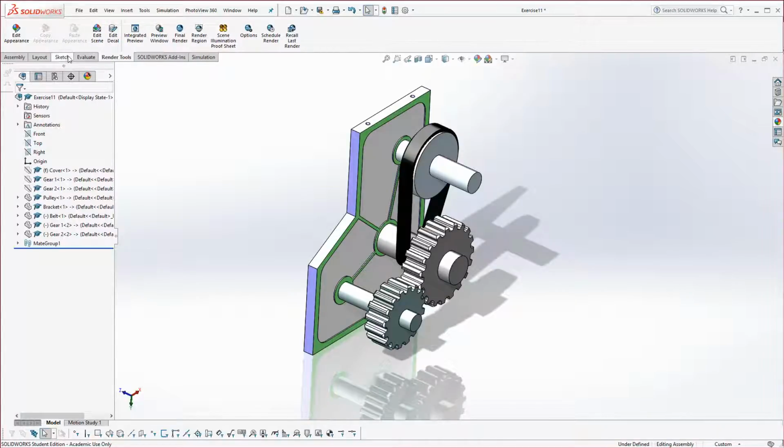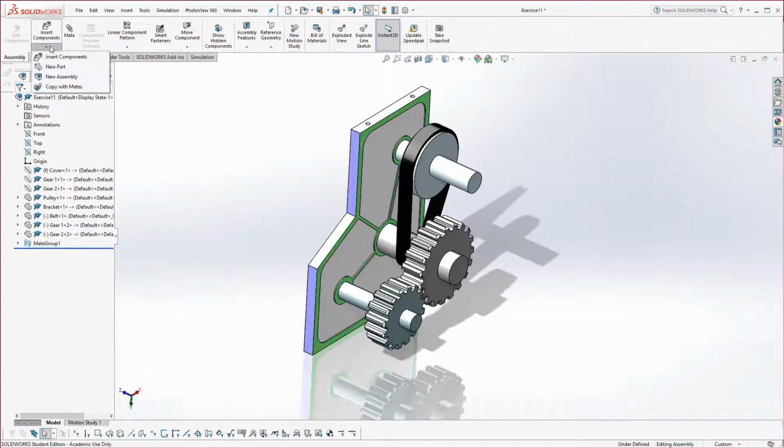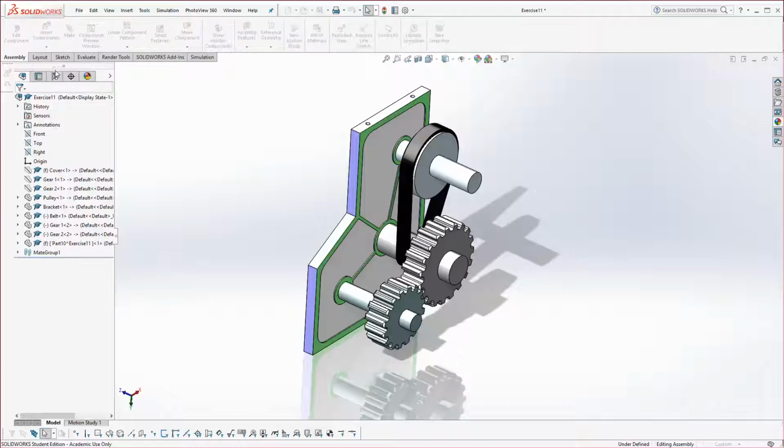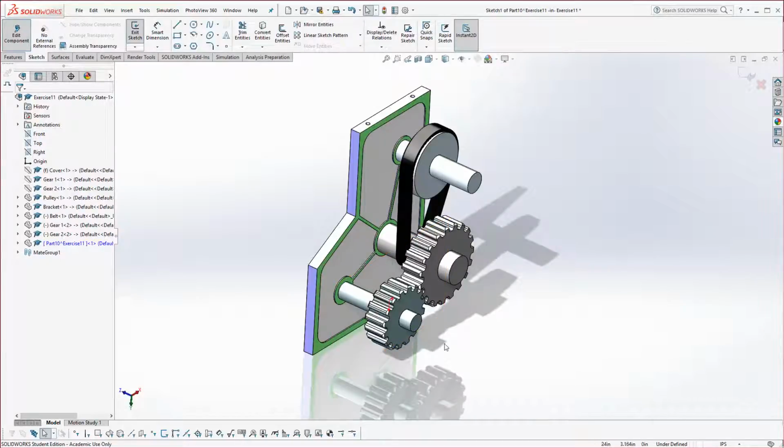So let's begin. First of all, bring up your sheet metal tools by right-clicking on any of the tabs that are here. And before you do that, actually, one thing you'll notice, sheet metal is not there. That's because we're currently editing an assembly, as you see down in the lower right corner. So we first need to insert a new part, then it will enable us to find that. So let's go to New Part, and go ahead and just drop it in on the front plane of the assembly over here in the feature tree. Where that lies is approximately just on the surface of the ends of these bosses. So that's perfect for us because that's as far as we want it to extend for the enclosure.